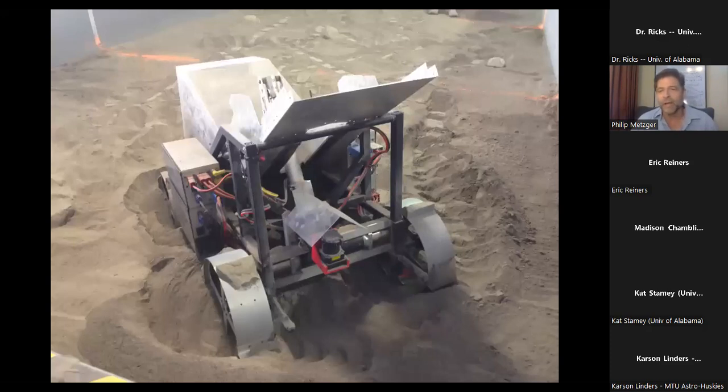But you see, here's a vehicle they were trying to turn. As they were turning, they were scraping the dirt sideways because they did not have any active steering. It was skid steering. Now, skid steering is okay. You can make it work, but it's one more factor that reduces your margin. When you're trying to drive with skid steering, you are shoving the dirt sideways a little bit. And that provides extra resistance to the motion you're trying to induce. You loosen the soil, it begins to get fluidized, and now you can see there's semicircles of fluidized soil flowing down into the wheels.